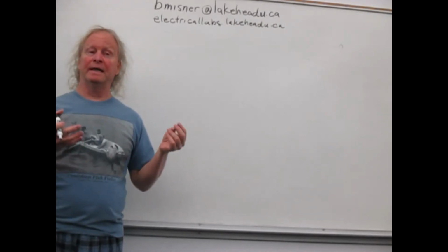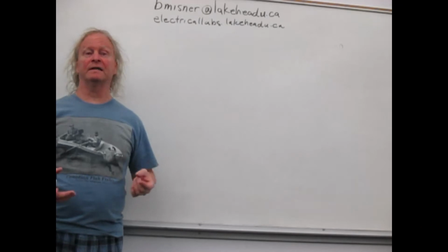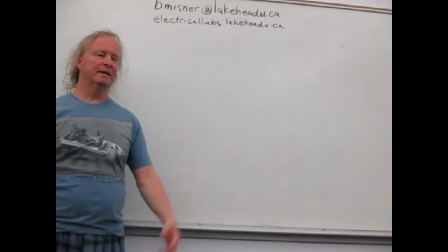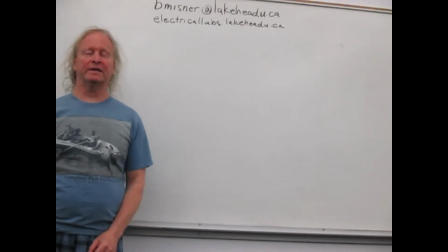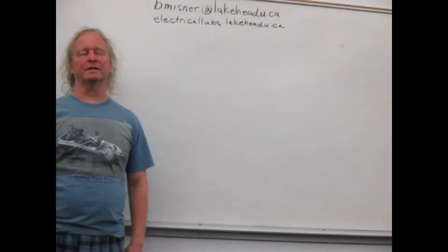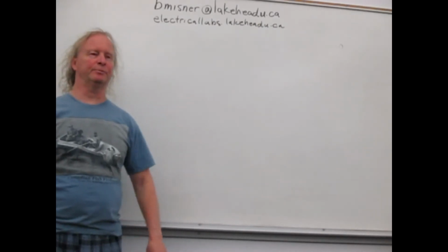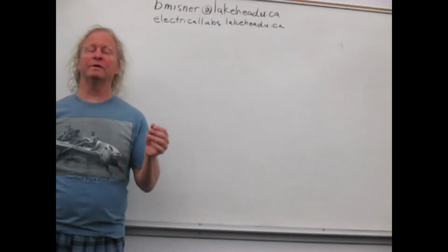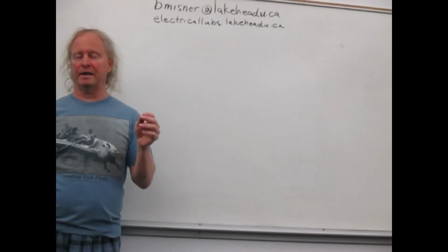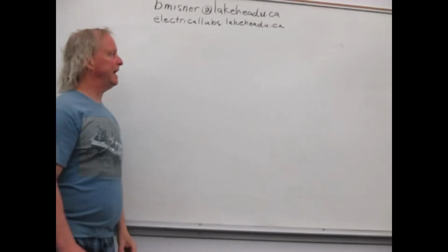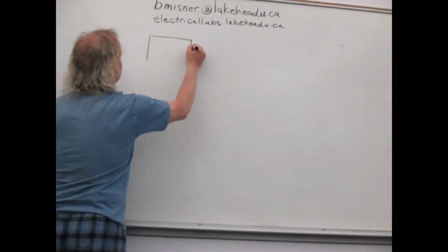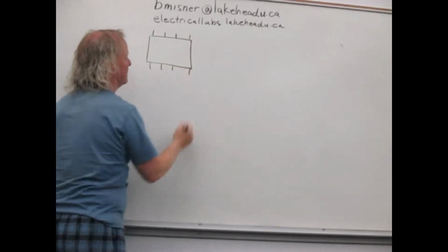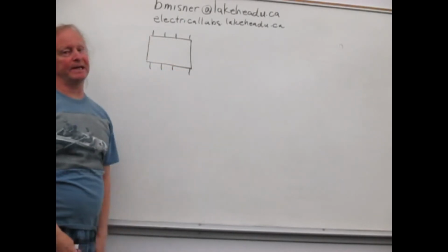Anytime you're using a device, or even transistors, the main thing you've got to do is get the data sheet for the device. So you look it up online, you download the PDF, and you take a look at the device and all of its characteristics. It gives you sample circuits and things like that to help you through. But the very first thing it'll go through is the pinout of the device. Because what we're going to do, and I'll show you in the demonstration, we use integrated circuits, ICs, right? And they're going to look like this. So it's going to have 8 pins on the IC.